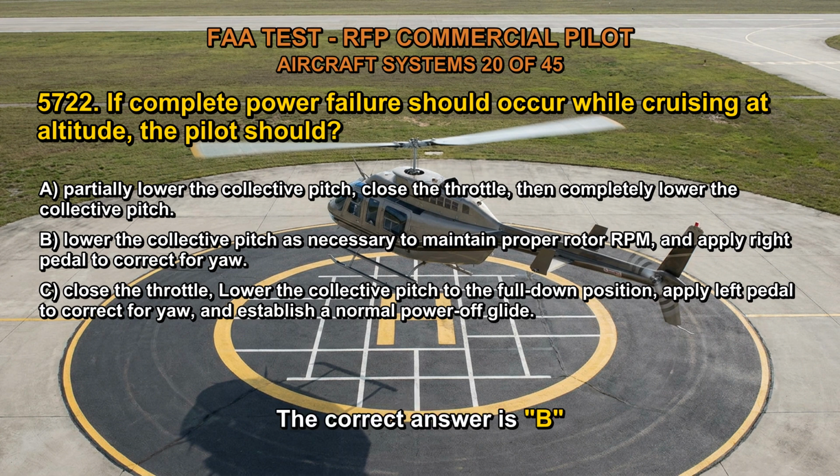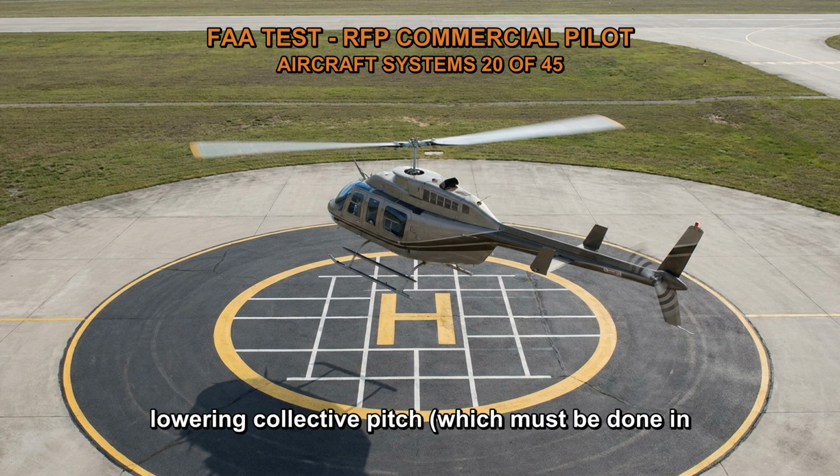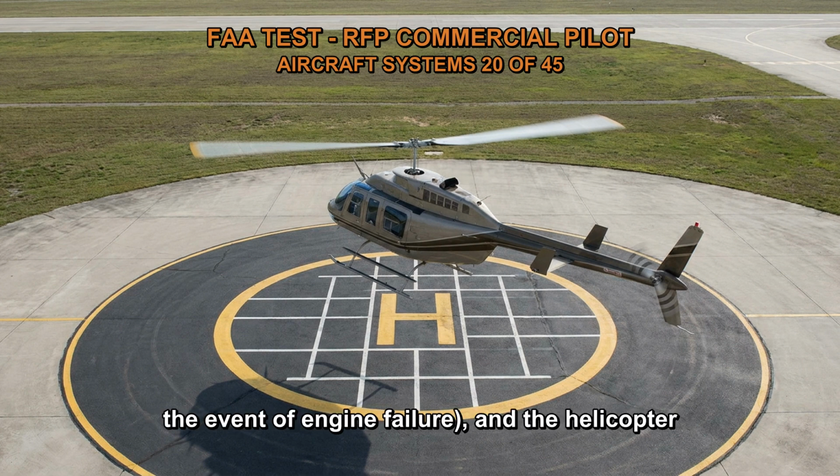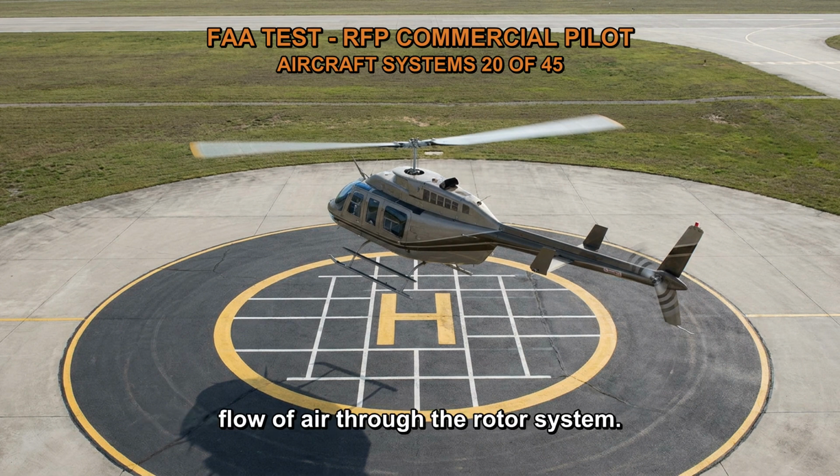The correct answer is B. Lift and drag will be minimized by quickly lowering collective pitch, which must be done in the event of engine failure, and the helicopter will instantly start to descend, creating an upward flow of air through the rotor system.